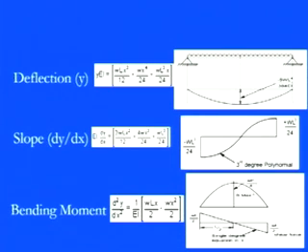And then again we can go for the bending moment and the shear forces, which we discussed many times. By differentiating these things, what we have is d2y by dx square, which is equal to 1 by EI times (WLx by 2 minus Wx square by 2).